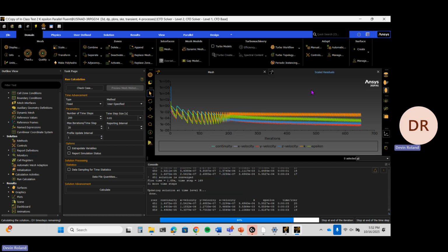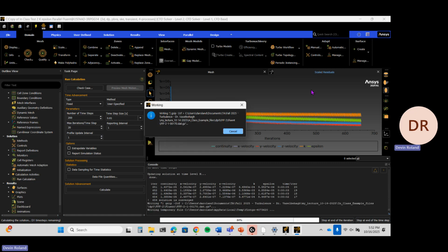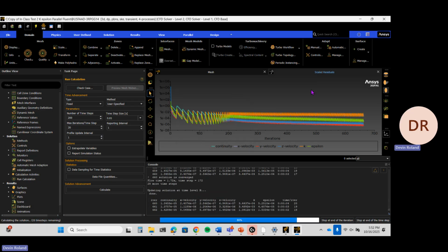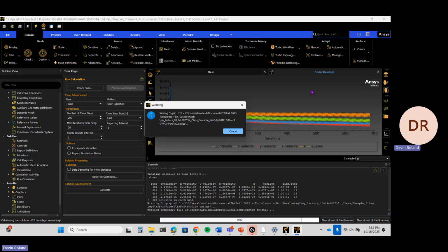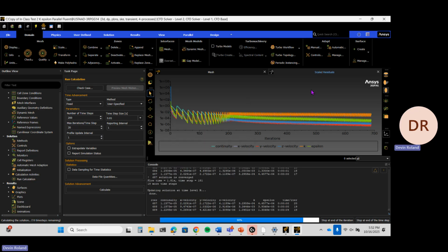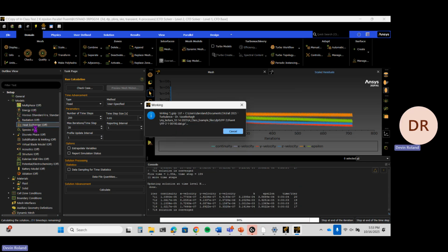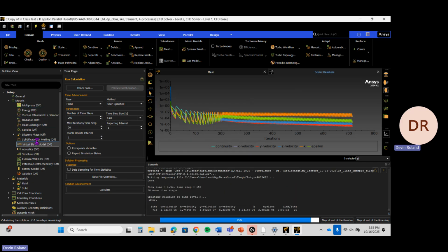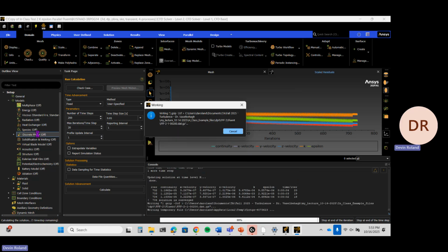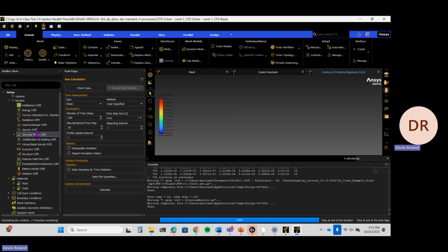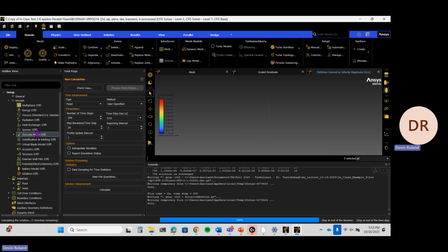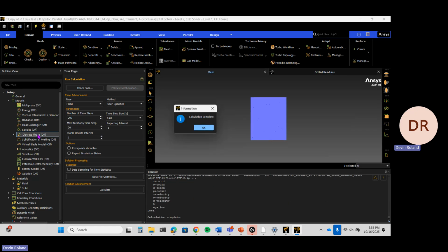Yeah, and there's also the schemes in CFD, the different schemes: first order, second order, third order schemes. And each one of these models that you can go up here and check: energy, radiation, discrete particle tracking. And even for discrete particles, you can have one-way coupling or two-way coupling, where the fluid affects the particles and the particles affect the fluid. You can choose, but all of that's going to add more equations you have to solve for each iteration, each time step.